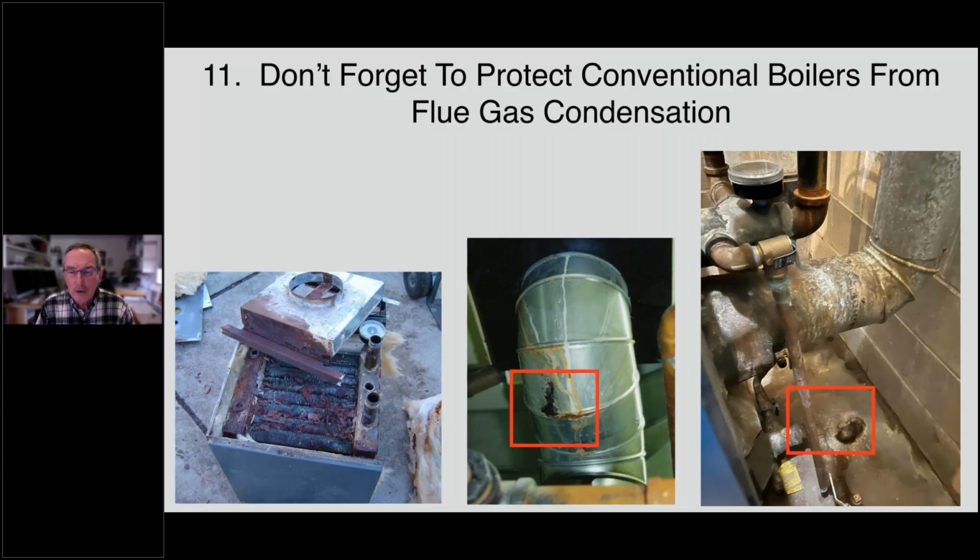Well, this was a boiler that was installed for several years, and it supplies radiant floor heat. And there was no provision to boost the inlet temperature to that boiler so that the boiler could operate above conditions that would cause sustained flue gas condensation. And then there would be a mixing device of some sort farther out into the piping that would reduce the water temperature. So yes, we could operate the floor at 95-degree water, but we don't want the boiler to have, let's say, 90-degree water or even 100-degree water coming back into it.